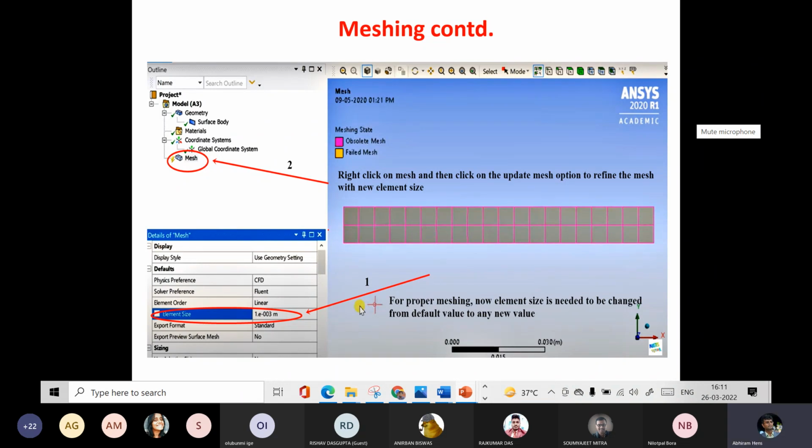So mesh means what? In the finite difference method, what we were doing, if there was a rod or a fin like this, was dividing the domain into a number of points, right? And at these points we try to solve the differential equation. Now these points are called mesh or grid. So you have to generate the mesh in this domain. Once you click the generate mesh button, it will by default create the mesh in its own way. Okay, so for example, you see that this is done, but it is actually a very crude mesh.